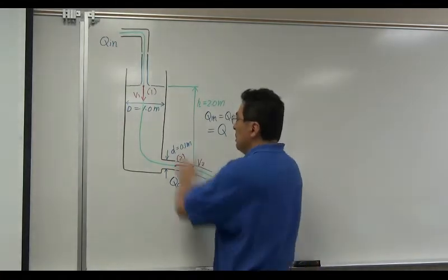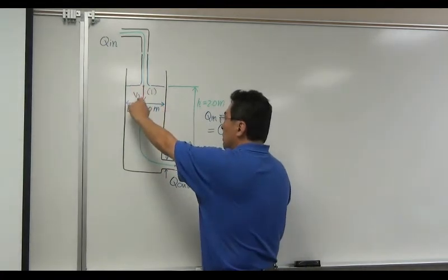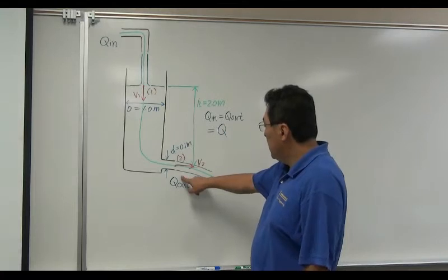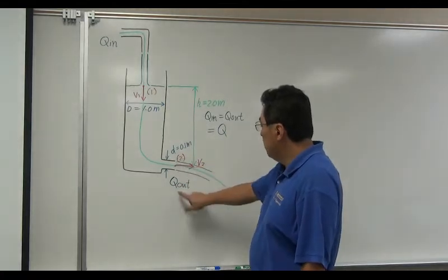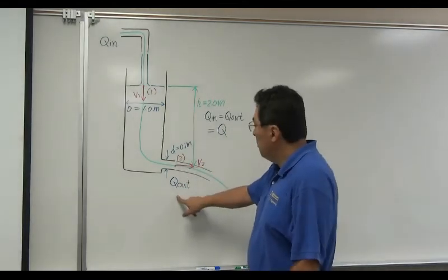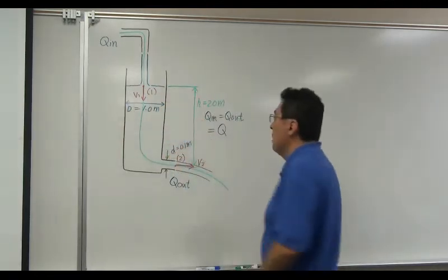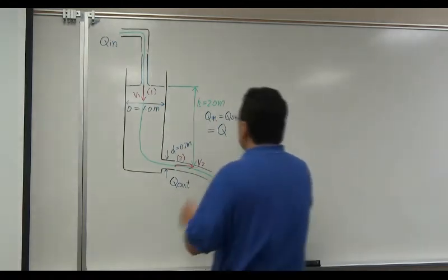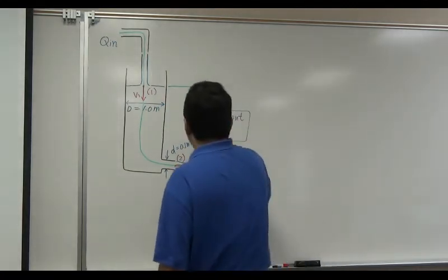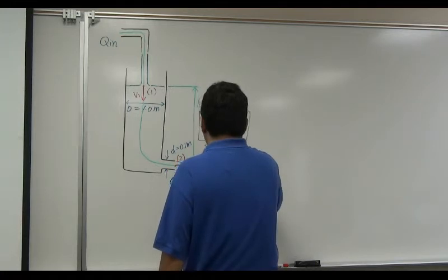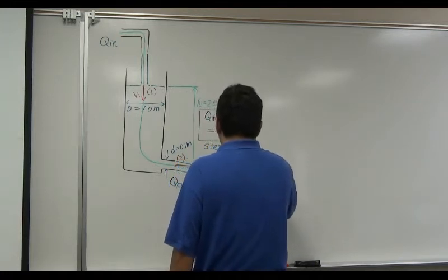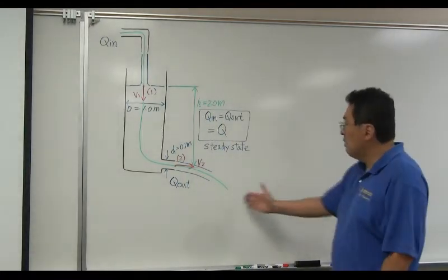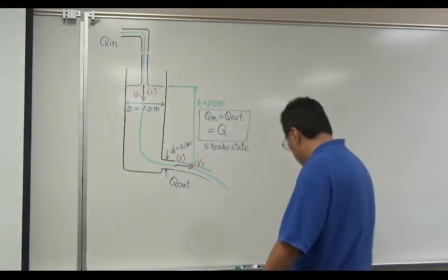So whatever the cross-section area here multiplied by velocity v1 gets you Q, flow rate, incoming. Velocity times cross-section area here gets you the flow rate outgoing. Flow rate in and out must be the same in order to maintain 2 meter depth constant. This is obviously a steady state problem, okay? That's why you can apply Bernoulli's equation along a chosen streamline. Okay?